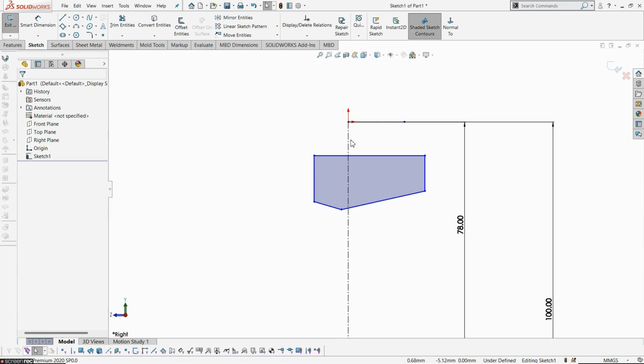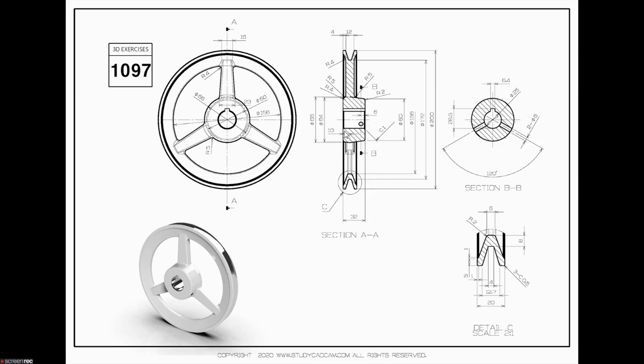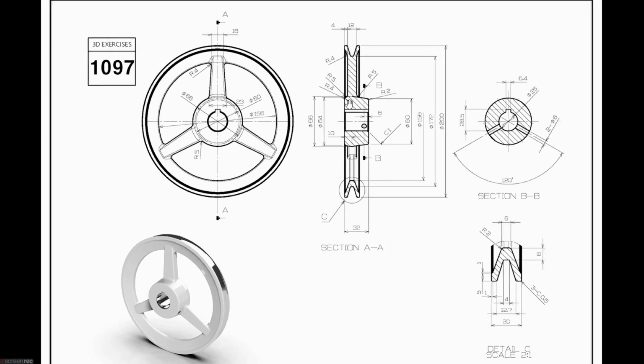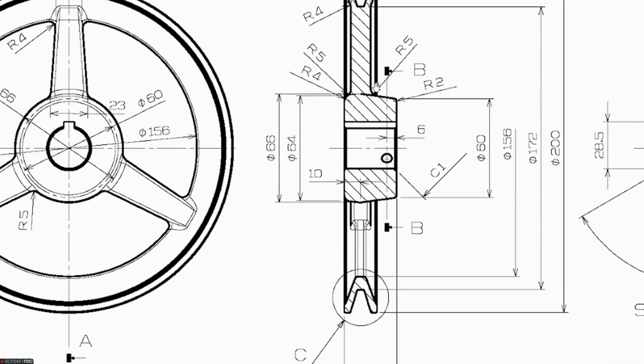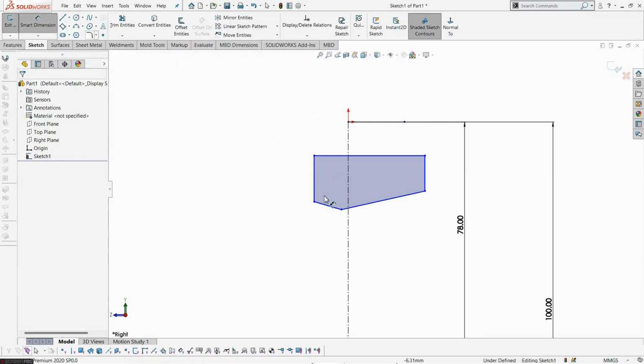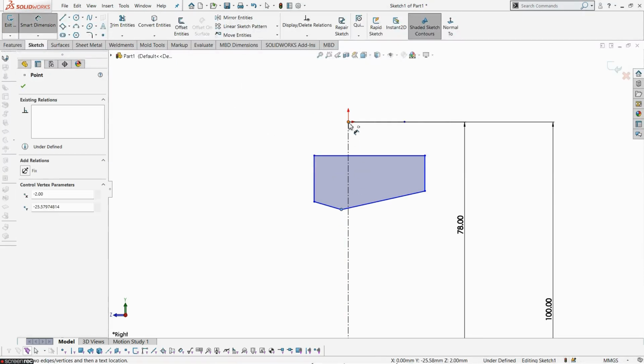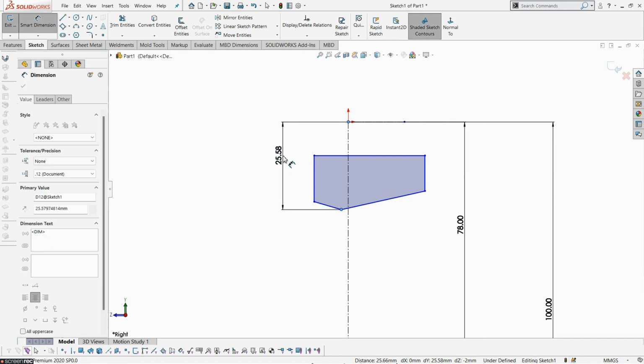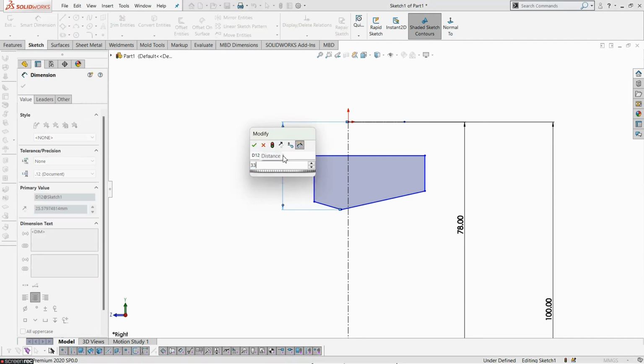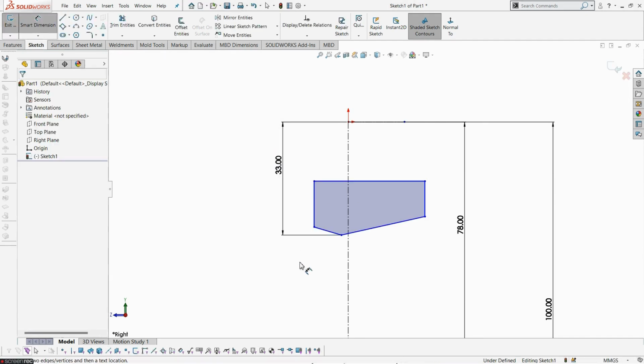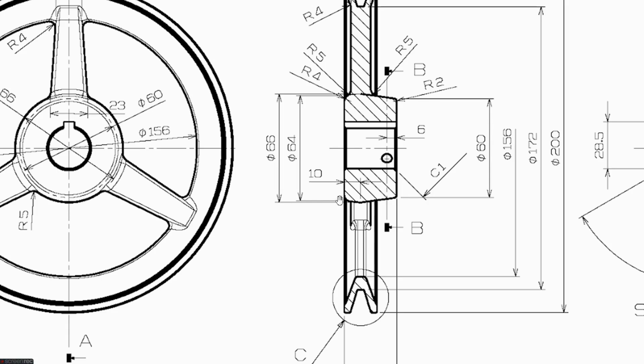Now what are the exact dimensions to fix this outer zone? Let's look at it clearly to go deeper. Zoom in on this area. Now the outer dimension is the point. It is 66 mm. Let's start from the 66 mm. From the origin, it shows half of the dimension. We need to mention only 33 mm. That is considered as a radius.